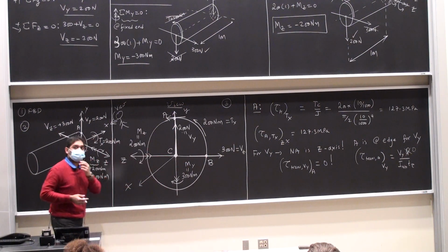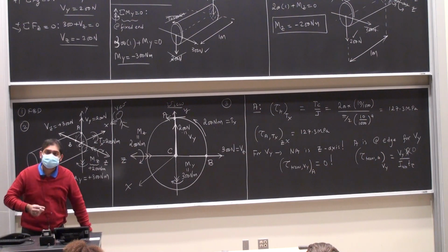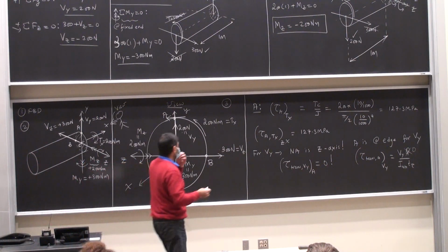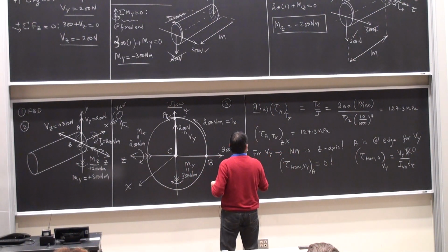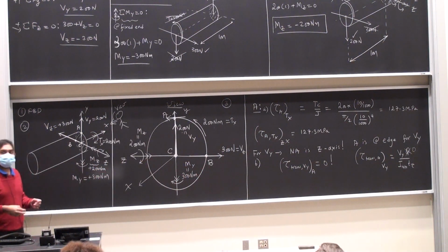And likewise, piece by piece, we look at each and every element that acts on that point. So you're evaluating the shear stress caused by the applied torques and the other two forces. Right, so we have taken care of one of them. So we call that as that. Then this is B. I need to do the same thing for Bz, 300 newtons.